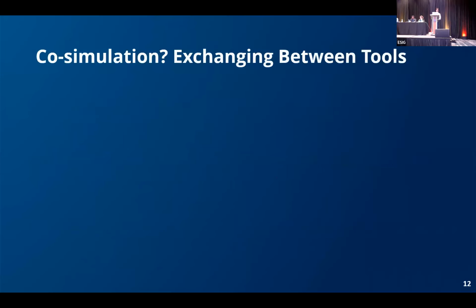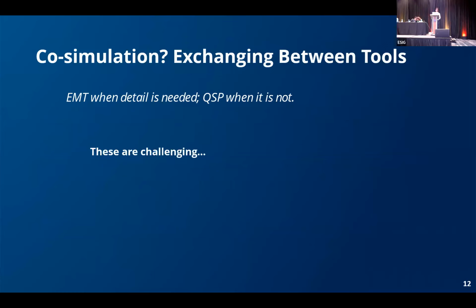So we could look at simulation. This is the exchanging of data between tools. So if I have 2 commercially available software tools like PSCAD and PSSE, can I carve out regions of those networks and model them in PSCAD and then model the rest of the system in PSSE? EMT detail when it's needed, QSP when it's not.